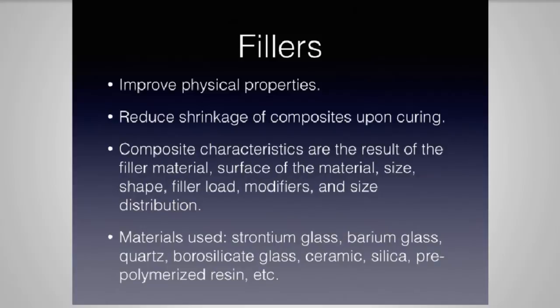Now let's take a look at fillers. Fillers are important because they improve the physical properties of the composite materials. They reduce the shrinkage of the composites when cured. They create the characteristics of your composite. Your characteristics of your composite are a result of your filler material, the surface of the material, the size, shape, load, modifiers, and size distribution.